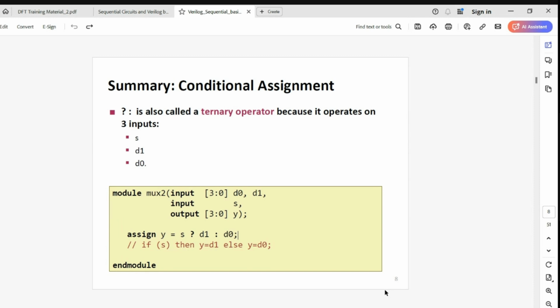So when you have a situation of mux, you don't know which input you want to decide now itself while writing RTL code, then you make it as a question mark. You decide on usage. Based on the usage, it will change. You want to select S to be 0 or 1, it will change later when you synthesize or when you use it in another module. Okay, understood?